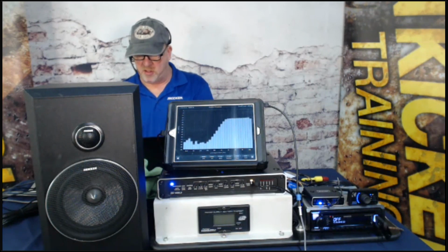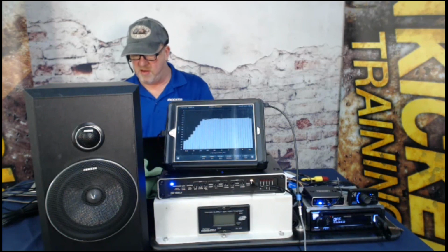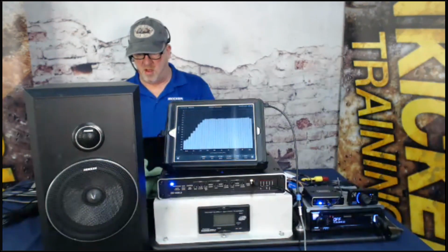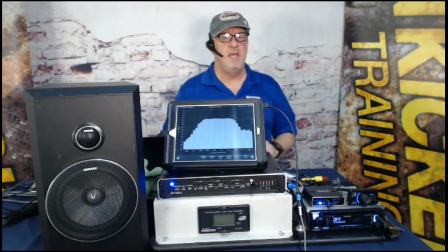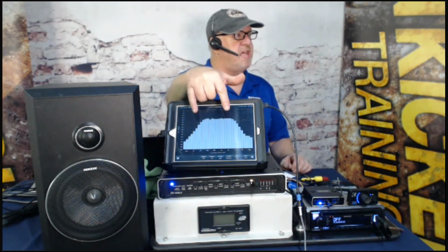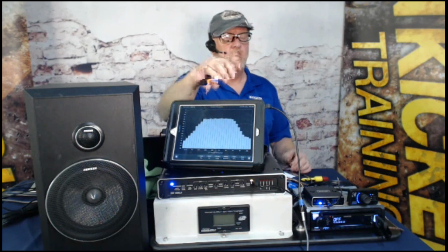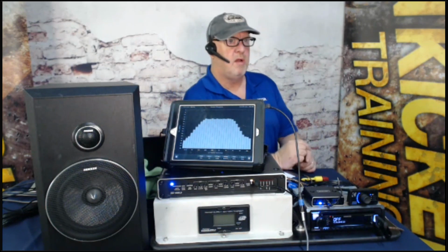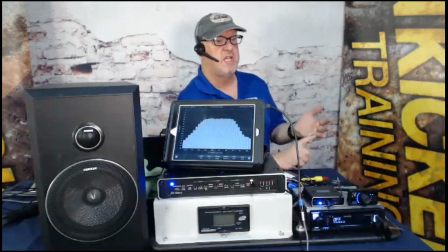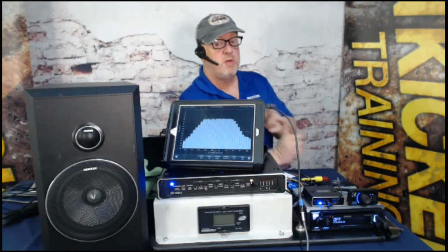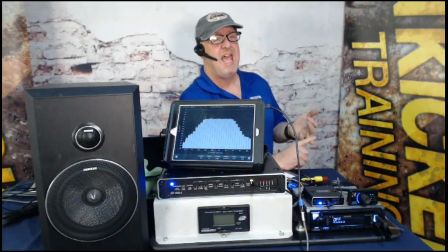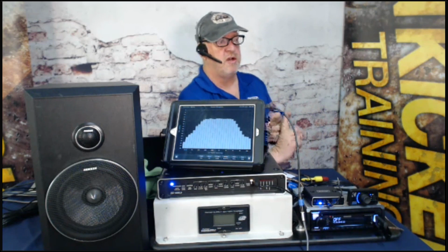So let's do a high pass crossover at 150 hertz. Let's do a low pass crossover at, say, 3,500 hertz or 2,500. Turn that on. Now what you see is a band pass. This is passing just a band of frequencies, which is very common in a high-end, three-way system. You've got a woofer, which is going to be low pass, a mid-range, which will have a band pass crossover, and then a tweeter, which will have a high pass only crossover.